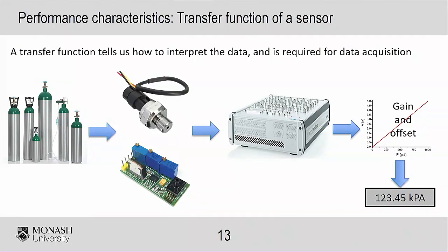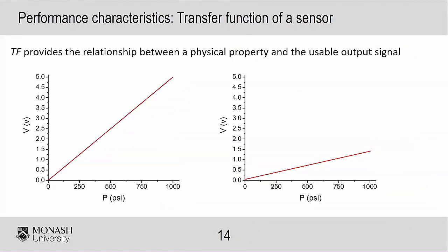So this is an example of where that is very useful. If we have two different sensors, let's say we start with the sensor on the left in whatever we're doing. Let's say we're testing a new medical device. Now we've put in, in this case, a pressure sensor. We know the transfer function of that sensor. It's working fine. We then discover that the sensor's broken and we need to replace it. And we replace it with the one on the right there. Can anyone tell me what we would do to the transfer function to get this new signal in that's quite accurate? Any thoughts?